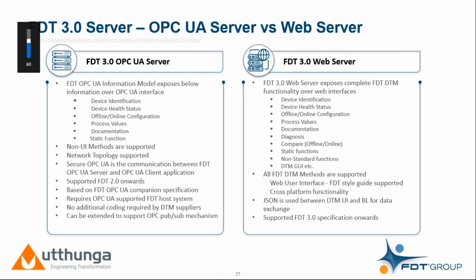And apart from this, via the OPC UA information model, we can also expose non-user-interface methods, meaning methods that do not require user interfaces. Just to give an example, reset the device configuration counter, which executes a small function inside your device and resets the device configuration counter, and does not require any user interface. These kinds of simple methods which do not require UI can be supported by the FDT OPC UA information model.